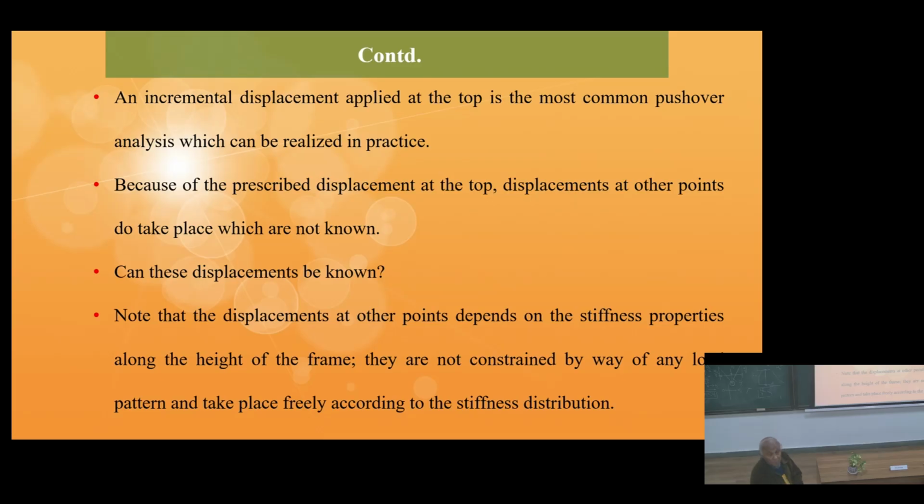Can this displacement be known? Note that the displacement at other points depends on the stiffness properties along the height of the frame. That's what I've told you. They are not constrained by any load pattern and take place freely according to the stiffness distribution. If I push it, it will have a shape according to the stiffness distribution. It is not constrained by any load pattern.